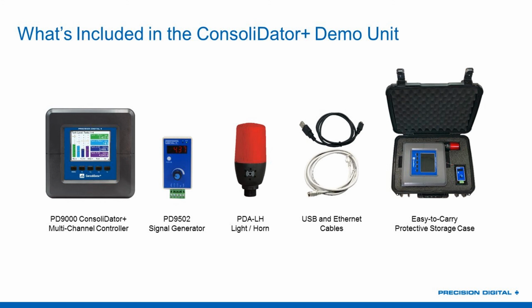And the answer to that was no. Unfortunately, you cannot do that, Tony. Though we are a master, we solely pull data out of those slaves. We really don't write calibration data back to them. Now, if that's something you wanted to do, keep in mind you can always do your calibration right in the Consolidator Plus. You could recalibrate it so that if you have issues with your calibration, rather than recalibrating your sensor, you could just rescale the consolidator and take away any of that error.